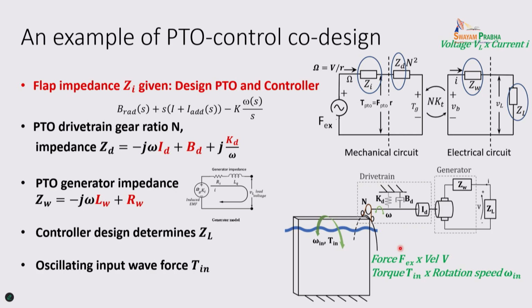Previously, we always said, now you match the frequency, then stiffness and inertia are cancelled. Then you have force and velocity in phase. In that way, no matter what you do, you always maximize the power, right? I give you an example, the swing set. You push in phase with the velocity, then the swing goes higher and higher. That makes sense, right? You have an ideal system, you have more mechanical power, then you will have more electrical power.